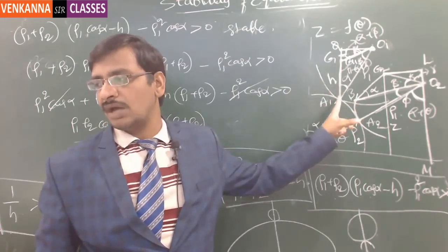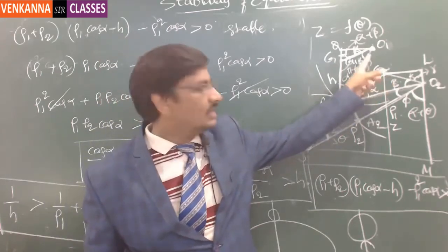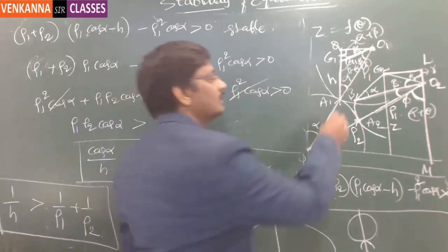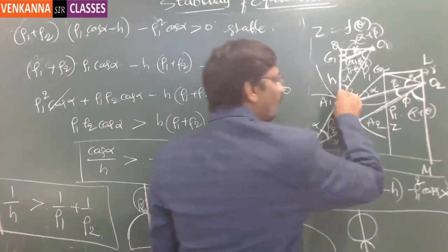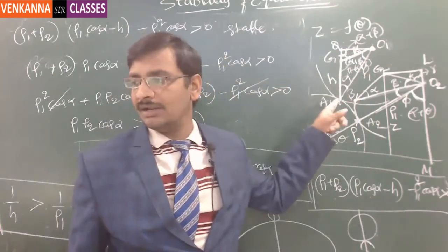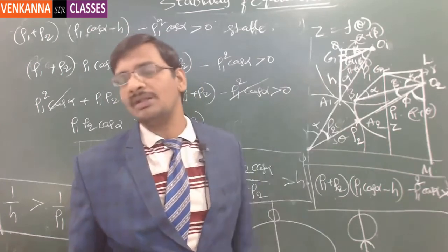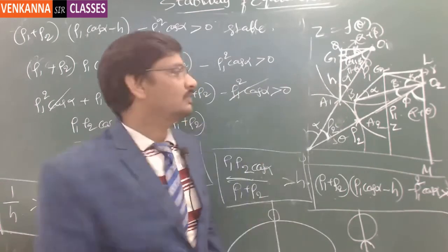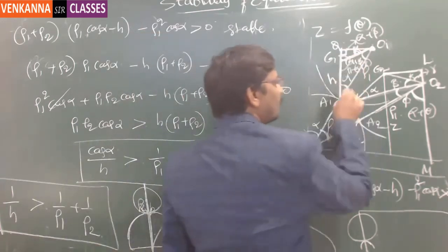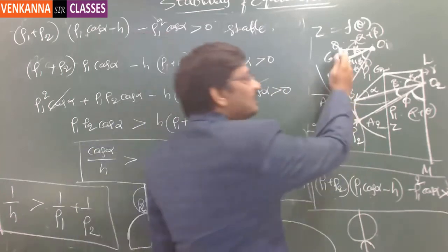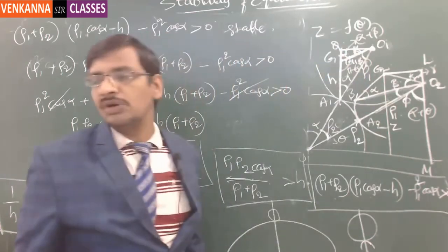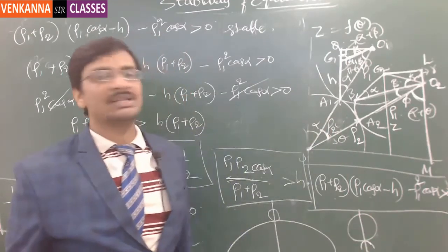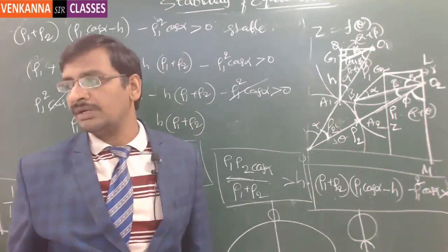Otherwise, if the center of gravity is here itself, then definitely it is going to fall down. And the fundamental rule is that this line is always vertical. Why? Because if it is not vertical, then the body is anyway going to be in an unstable condition, because the center of gravity has to be on top of the point of contact. Otherwise, if it is tilted a little bit, automatically it will fall down. It won't stay there itself. That means the body is not under equilibrium itself. Then there is no point in questioning whether the equilibrium is stable or not. Got it?